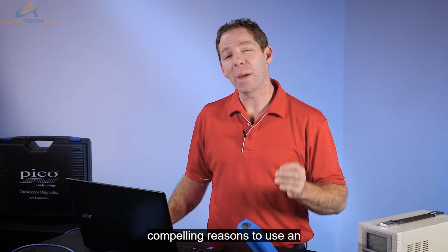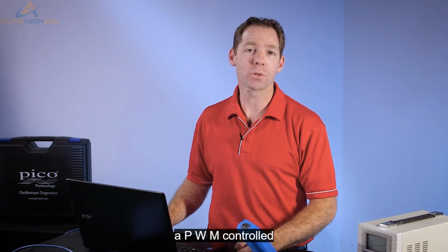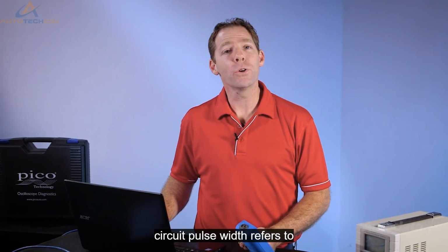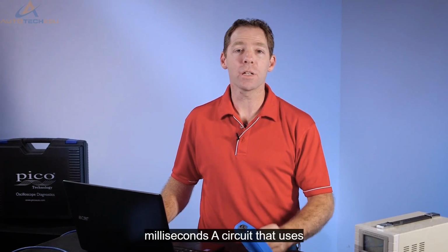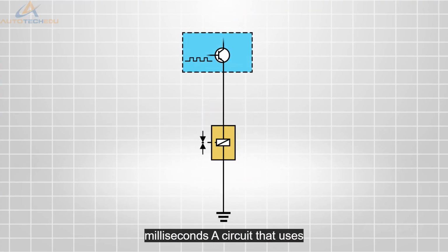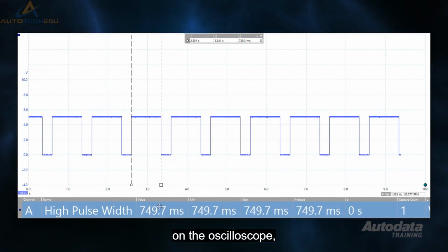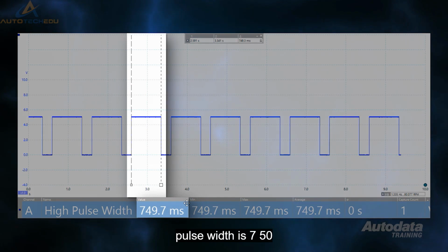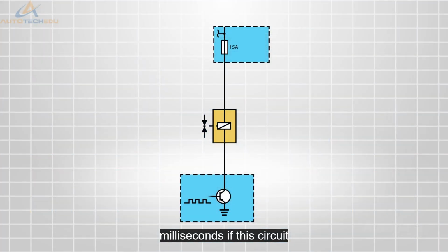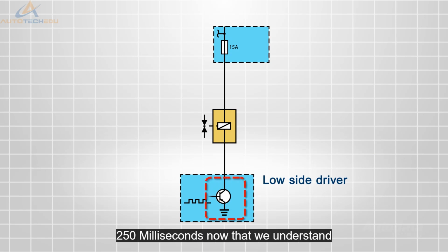This is one of the most compelling reasons to use an oscilloscope for any diagnosis on a PWM controlled circuit. Pulse width refers to the exact time the control is pulled high or low. This is measured in milliseconds. A circuit that uses a high side driver requires us to measure the pulse width when the voltage is pulled high. On the oscilloscope, we have a cycle of 1 second, so our pulse width is 750 milliseconds. If this circuit was controlled by a low side driver, the pulse width would be 250 milliseconds.